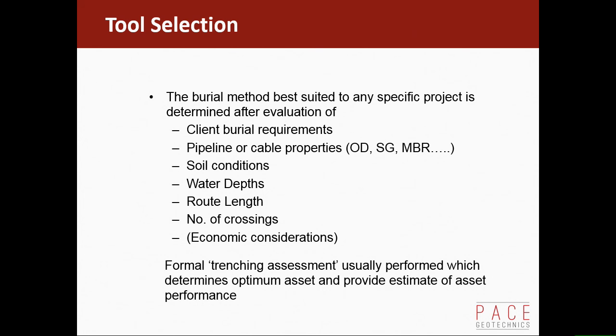A plough is much more efficient for a long route because they tend to be relatively fast. Certainly in stiff clays they are particularly good, but a disadvantage of a plough is if you've got a lot of crossings and you're working close to infrastructure, you're going to have to recover it, and they're big things to recover, whereas a jetting tool is much easier to recover.